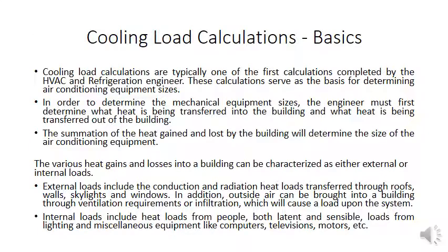In this basic cooling load calculation, this is the first calculation which is completed by the heating, ventilation and air conditioning and refrigeration engineer. So when you go to the market and project yourself as an HVAC and refrigeration engineer, the user may ask you what calculation you are going to do. You need to answer that you are going to do two types of calculation. First is external load and second is internal load.